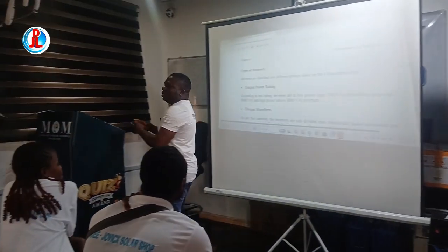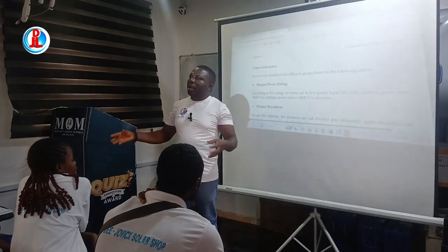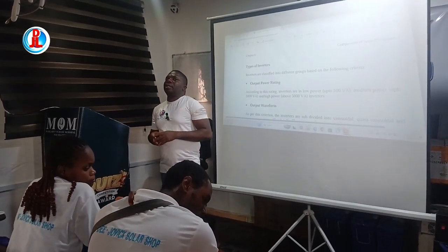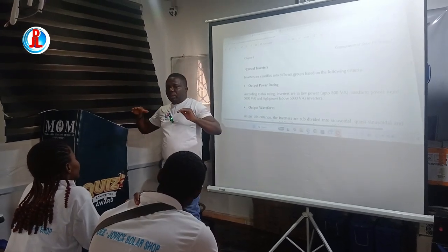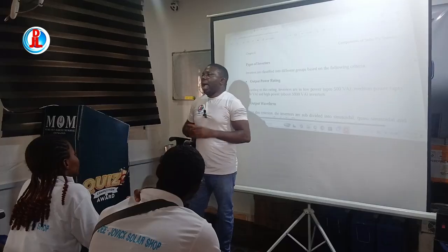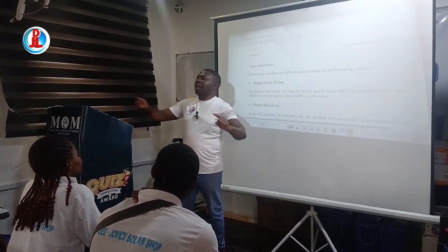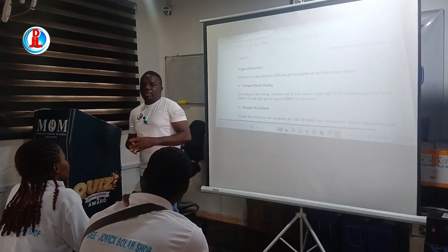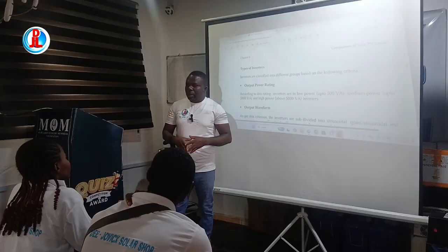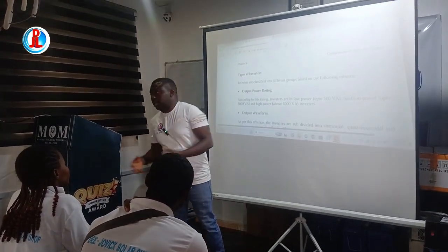Now that is an inverter for you. Now look at the voltage. The high voltage inverter operates with a very high voltage. The concept is that when the sun is going down, the voltage will still be normal for powering. Imagine I have a panel whose voltage is 32 and I connect all the panels in series. When the sun goes down, the voltage will go down. The voltage turns to 24 and the battery is 24, so it will not charge the battery again.